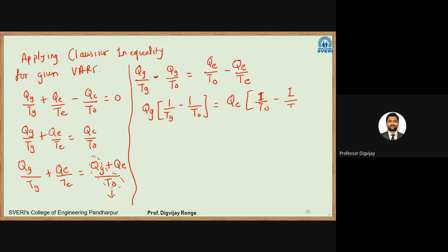Now, if our main objective in this case is to calculate the COP, COP will be equal to, what is our objective? Our objective is to extract the heat from the space, that is the QE. And what is our input? In this case, our input is pump plus generator heat. If I neglect the pump heat, see here, input will be equal to, I'm applying some pump work.